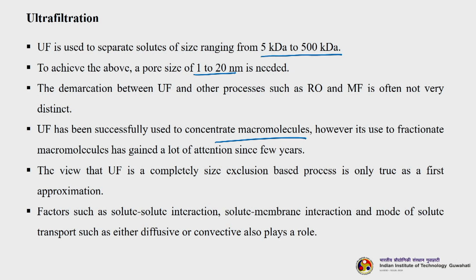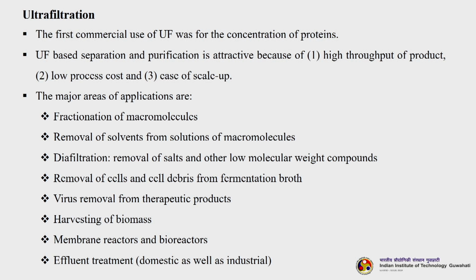So, the view that ultrafiltration is a completely size exclusion process is only a first approximation. As you know, there are many other factors that play a role in any membrane based separation. They are solute membrane interaction, solute interaction, and mode of solute transport. Especially in ultrafiltration, the mode of solute transport can be either diffusive or convective, or a combination of both.